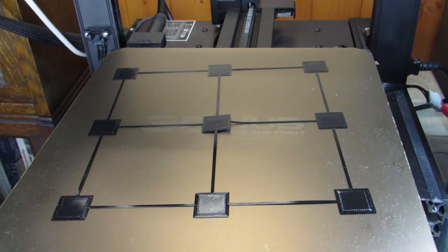Enjoy your printer. Don't get lost in the numbers too badly. But here is your answer for how do I get the offset correct, using the fact that the printer itself can tell me when it's touching the bed and when it's not, instead of trying to shine a light behind the nozzle like some people have to do on other models of printer, or instead of using a feeler gauge and subtracting the thickness of the feeler gauge from wherever your offset says you are. Try this. I think it works.